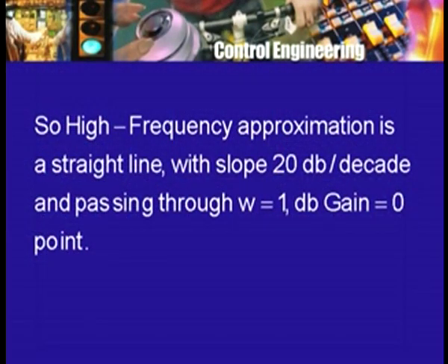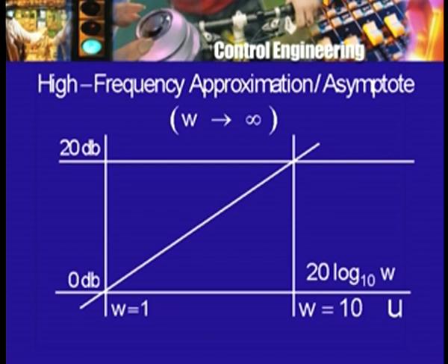So, for a moment if I just work with omega rather than f on the horizontal axis, then let us say here is my horizontal axis, and I am going to put here both omega as well as u. Although when we use the semi-logarithmic paper, the graduation along the horizontal axis is such that one should think of not omega but u.